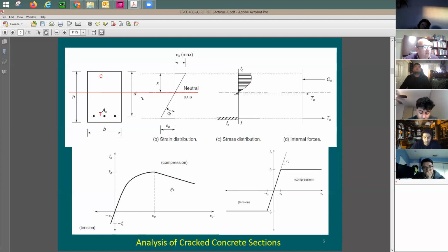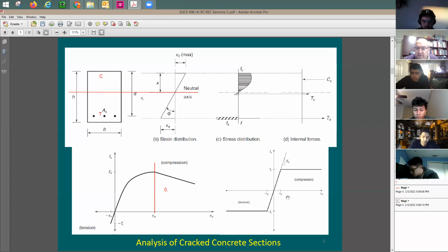Concrete is very good in compression. What did we say about failing of concrete? Where do I assume that concrete is going to be failing? Anyone remembers the value? We said concrete is failing at a strain of? Yes? Isn't it 0.3? 0.003. The code says it is true that the concrete is going to be able to attain higher strains, but for us, we say once it reaches 0.003, we just say concrete's gone.